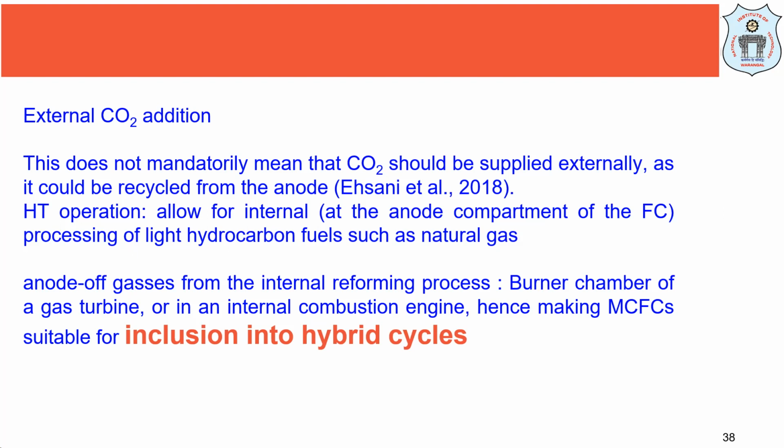And whatever electrolyte conducts carbonate ions, it is necessary to provide carbon dioxide additionally to the oxidant at the cathode to form the carbonate. So we are supplying carbon dioxide. This doesn't mandatorily mean that CO2 should be supplied externally. It can be recycled from the anode side also, because we have seen that you have CO2 being formed at the anode side. Okay.